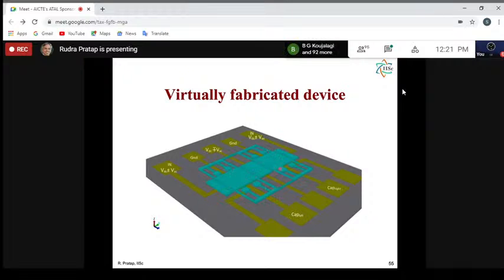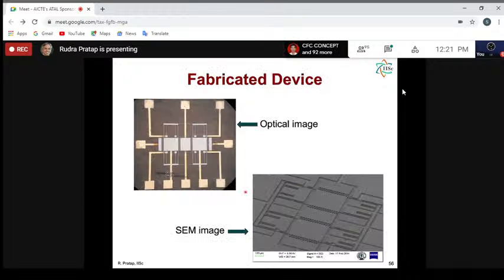You can first design this MEMS gyro in any of the many design software packages that you have, CoventorWare or IntelliSuite or whatever you have. And then this is the fabricated structure. It's an optical image of the proof mass, which is suspended by these beams, and the beams are anchored at these places.